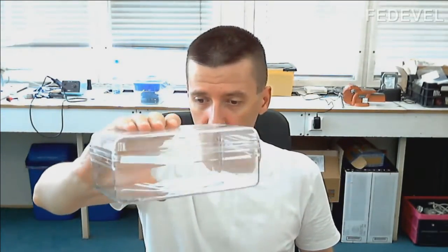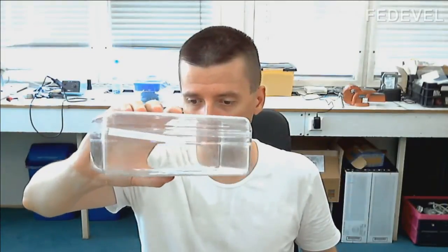Yeah, normally for resistors and capacitors it is just fine, but there are some footprints for chips which they say have the same footprint, but they may be a little bit different between manufacturers, especially the recommended footprint may be a little bit different, or also there are some different names for the same footprint.